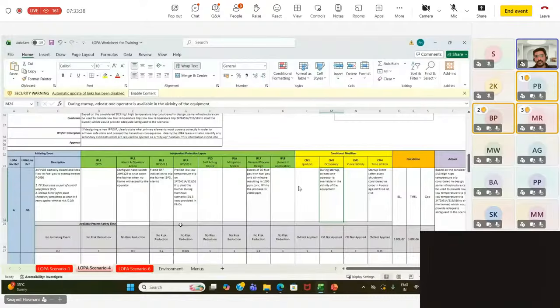Now, in this case, if you see excess of fuel gas with fuel gas and air mixture resulting, here also there is the same argument that there would be excess of fuel gas. However, in the earlier case, what was happening was that our fuel gas valve was continuously open, okay, and that was a blowout due to excess of carbon monoxide. In this case, your fuel gas flow itself is constricted. So your scenario is much less catastrophic than the earlier case, because your fuel gas, which is required for combustion, itself is constricted.